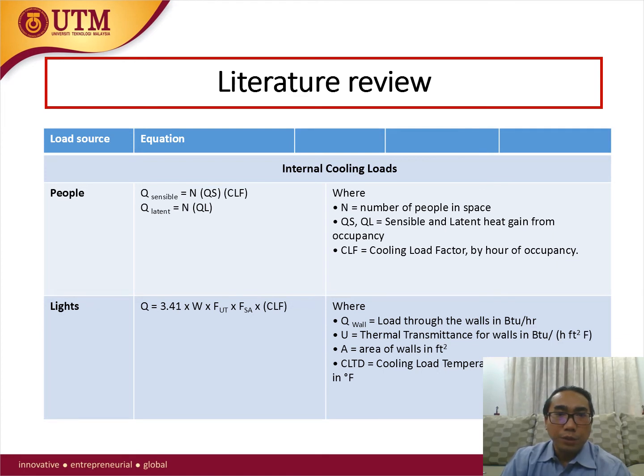The remaining portion is in the form of radiation, which affects the conditioned space only after having been absorbed and released by walls, floor, furniture, etc. This absorbed energy contributes to space cooling load only after a time lag, with some part of such energy still present and radiating after the lights have been switched off.